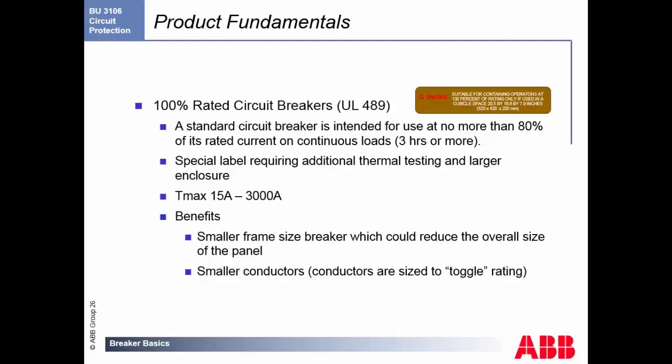Again, you don't want to press. That's the guideline I spoke to beforehand. Generally, you want to stay within 80% of the rated current. You don't want to push things to 100%. It'll work, but it's not the safest way to use the product.